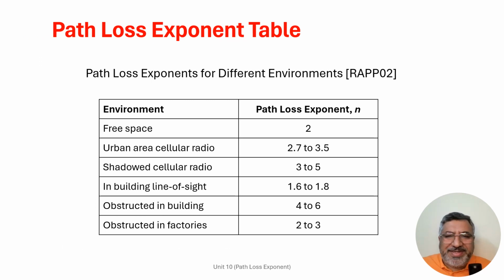In wireless communication studies, practically path loss is represented by the path loss exponent, whose value is normally in the range of 2 to 4, where 2 is for propagation in free space and 4 is for a relatively lossy environment, and for the case of fully specular reflection from the Earth surface, referred to as the flat Earth model.